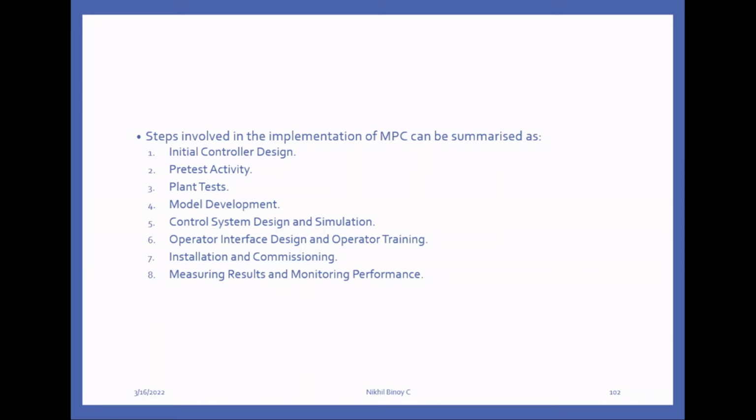First step is initial controller design. Second step is pretest activity. Third step is plan test. Fourth step is model development. Fifth step is control system design and simulation. Sixth step is operator interface design and operator training. Seventh step is installation and commissioning. And the last step is measuring results and monitoring performance.